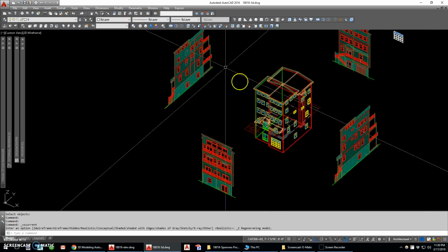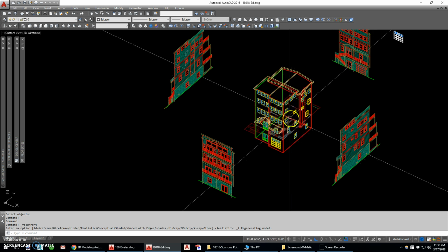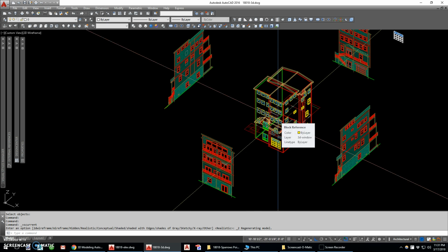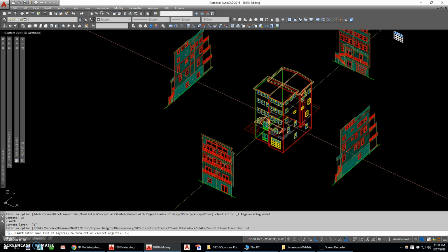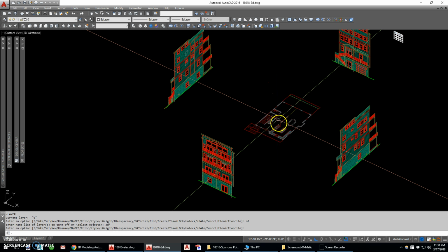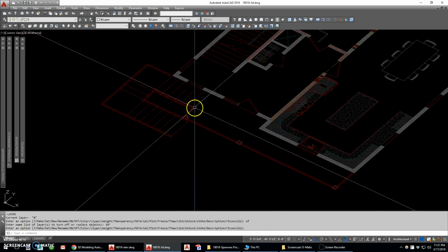First thing I'm going to do is look at the shape of the deck. Now, this is why we put all our layers on layer 3D. I'm going to turn layer off, star dash 3D star. That didn't work. Layer off, I'm sorry, 3D star. I'm just going to take a look at the shape of this porch.